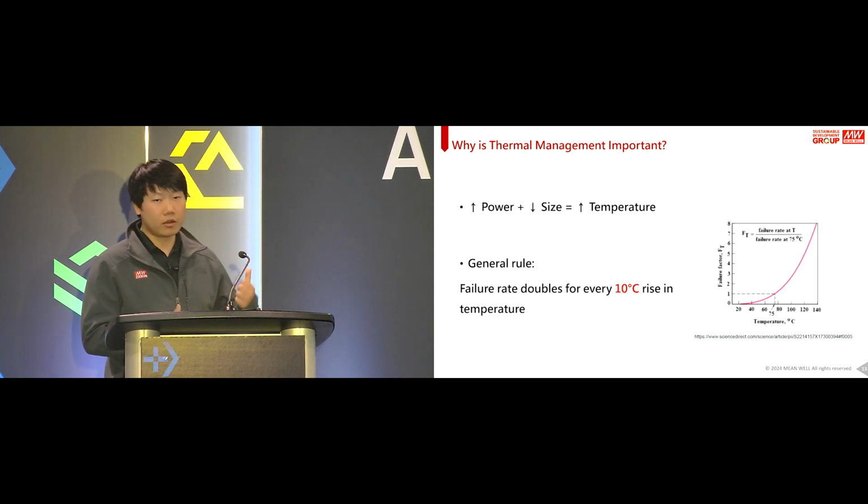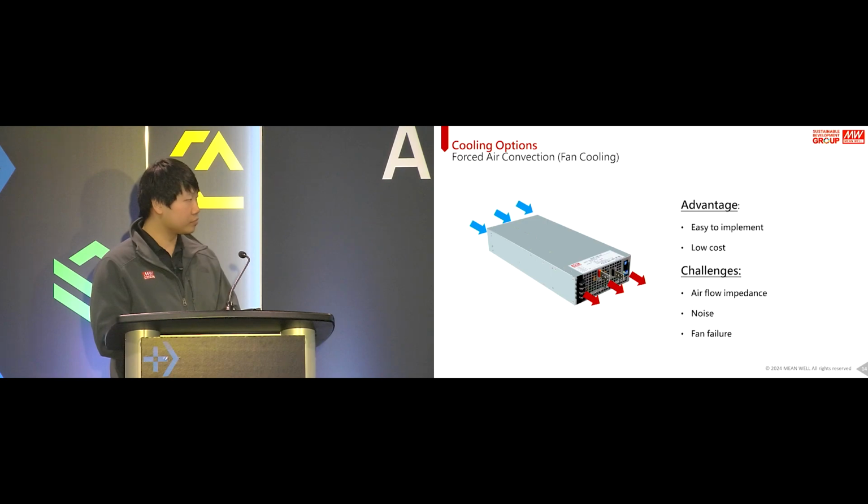So we're asking for higher power and lower size, which means that internal to the devices, the temperatures will go up as well. The general rule of thumb is that the failure rate doubles for every 10 degrees Celsius rise in temperature. So we want very good thermal management in order to have a reliable power supply integration.